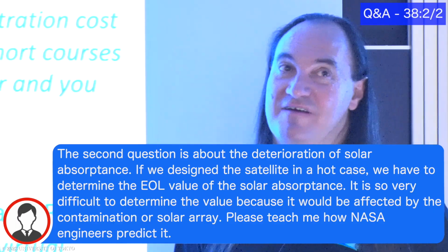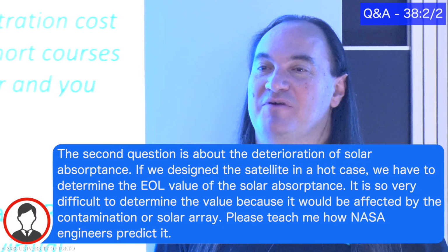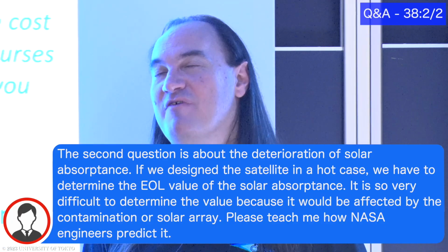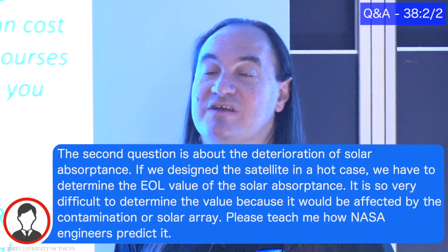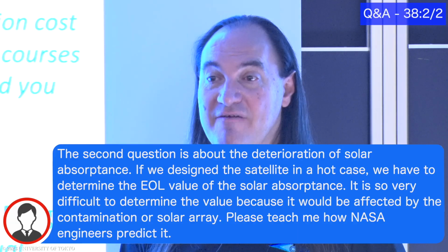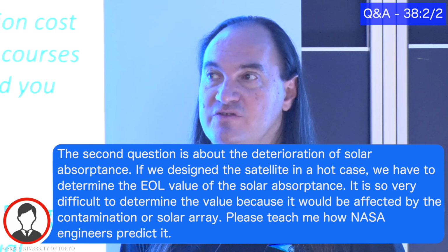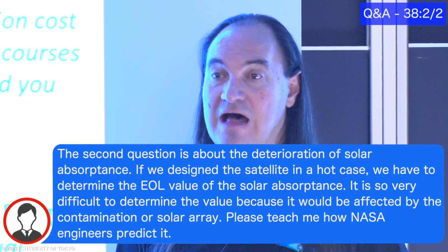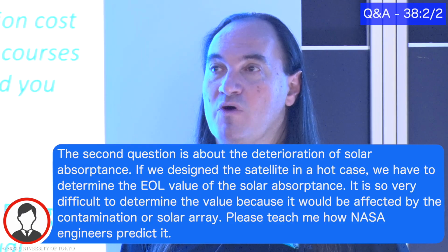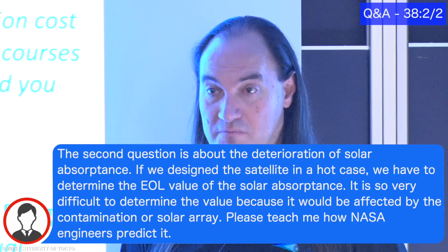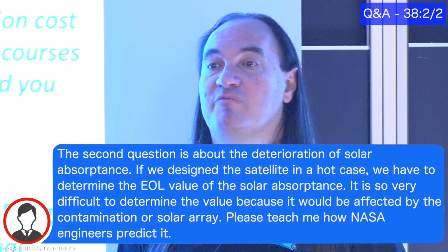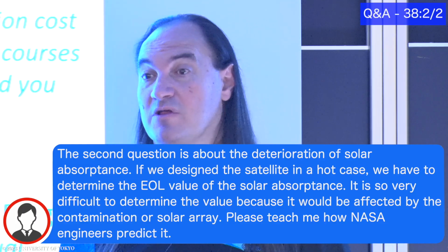So basically, if I understand, how do we get our EOL numbers? I'm in code 545. Right above us is code 546. They are coatings and contamination. And their job, and one of the gold rules we have at Goddard, is that the coatings committee, a group of people who are knowledgeable about how coatings degrade, how they perform, will specify for the thermal team what the acceptable values of properties to use for the thermal analysis are.